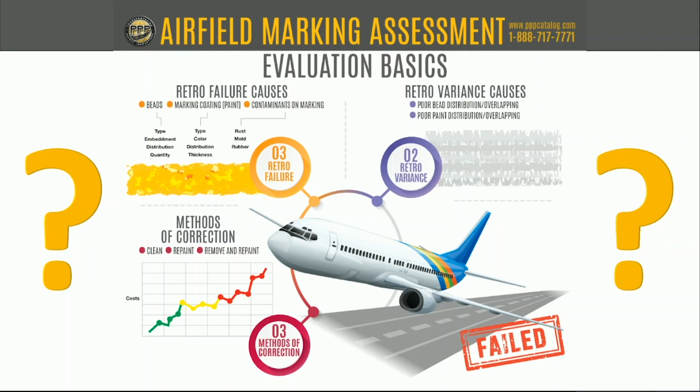Well, as far as the inlaying, as a general practice, we do not do that. One of the reasons, I think, is that roads get overlaid a lot more often than airports do. So if anything changes, and now you have this inlaid marking that has to move, that represents a much larger fix. With respect to the question itself, with an airport that does a lot of snow removal, how can you increase longevity?